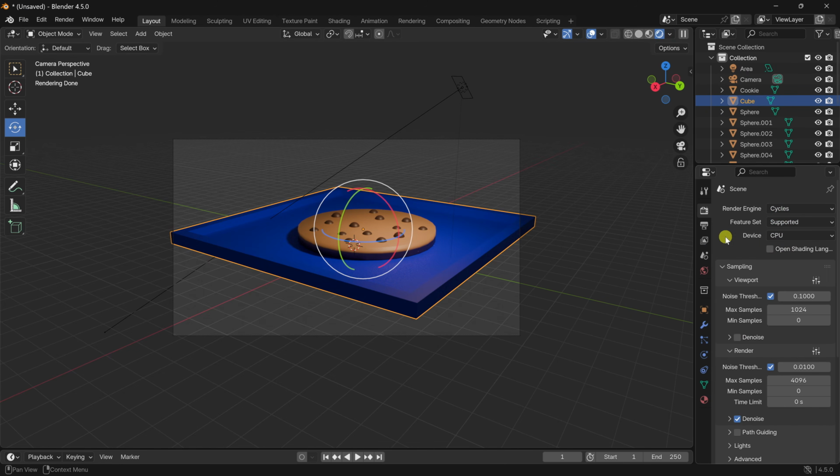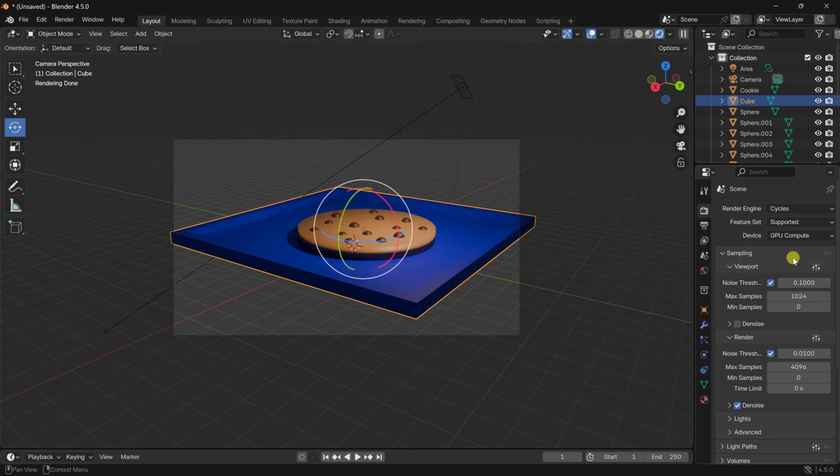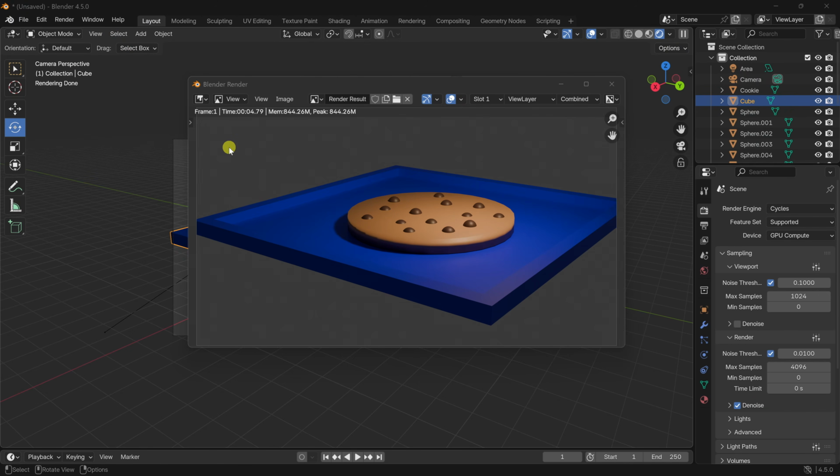I like the way this one looks. So I'll use Cycles. Down below, you could also select the device. Currently, it's set to my CPU, but here I could also switch it to my GPU. I'm now all good with these settings. So up on the top bar, let's click on render. And here we have the option to render the image. Now right over here, you'll also see that the shortcut key is F12. Let's click on this. It's now all done rendering.